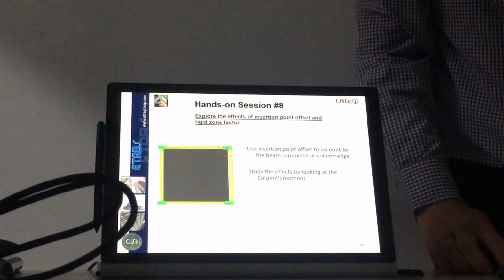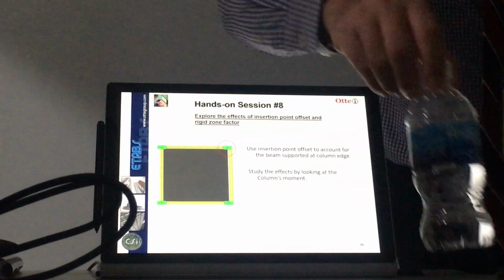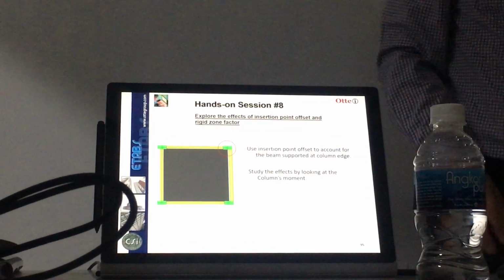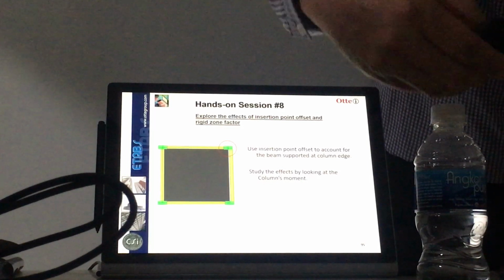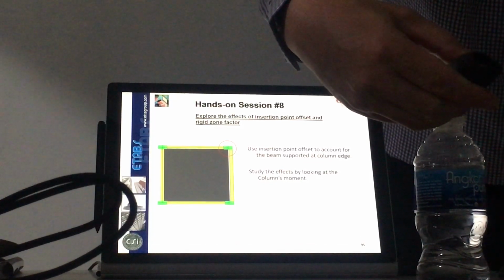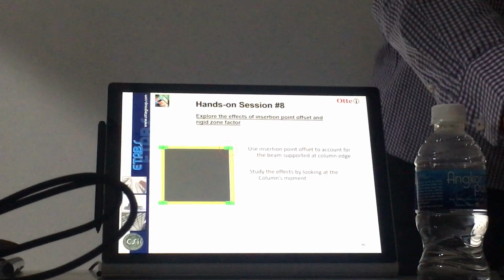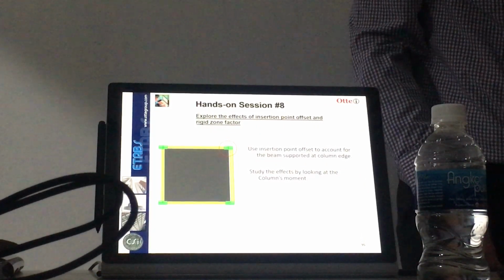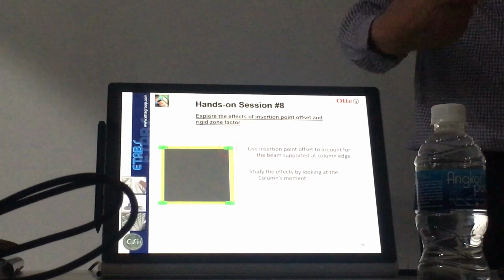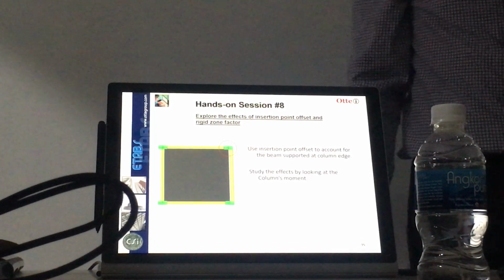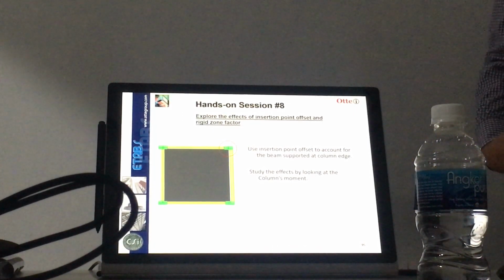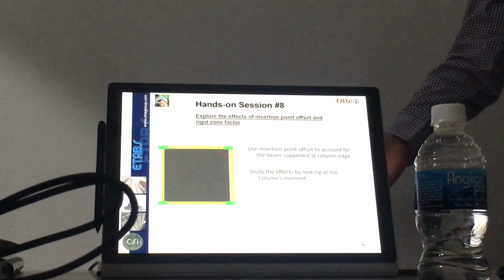But actually, the only thing that represents it is this dot in the center, right? So if my beam is coming in, I should connect here. It's called connected. But sometimes this is very wide. I want to put my beam on the side. So coming is here, right? Let's imagine that coming here. This dot and this dot never connect. So is it connected? No.